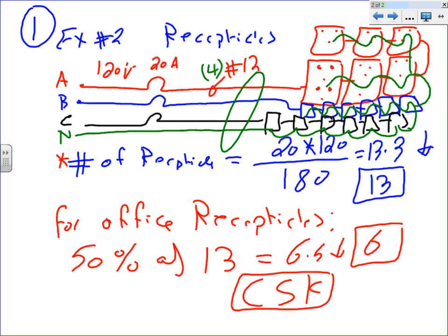Another way, Brooks, probably some people will do, they bring phase A here, phase A, B, C, A, B, C, A, B, C, and they stagger them. And that's a better way of doing it, more expensive. So I bring a three-phase circuit right in here. I put this one in phase A, this one in phase B, circuit 1, circuit 2, circuit 3. Circuit 1, circuit 2, circuit 3, and you keep doing it. What's the disadvantage of this? You're pulling more wires. What's the advantage? More power in one location.